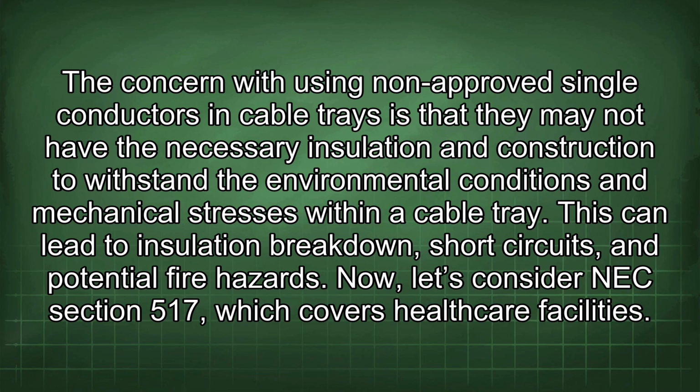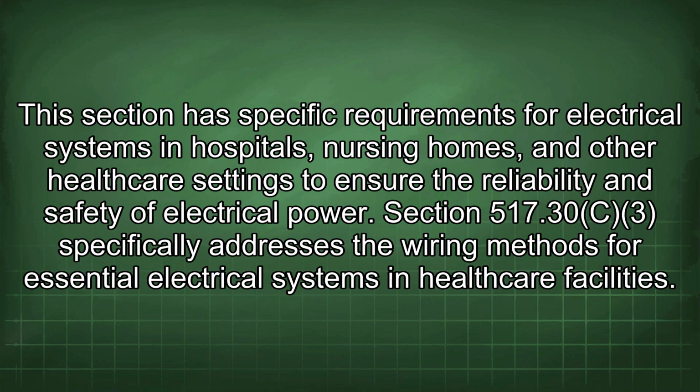The concern with using non-approved single conductors in cable trays is that they may not have the necessary insulation and construction to withstand the environmental conditions and mechanical stresses within a cable tray. This can lead to insulation breakdown, short circuits, and potential fire hazards. Now, let's consider NEC Section 517, which covers healthcare facilities. This section has specific requirements for electrical systems in hospitals, nursing homes, and other healthcare settings to ensure the reliability and safety of electrical power.